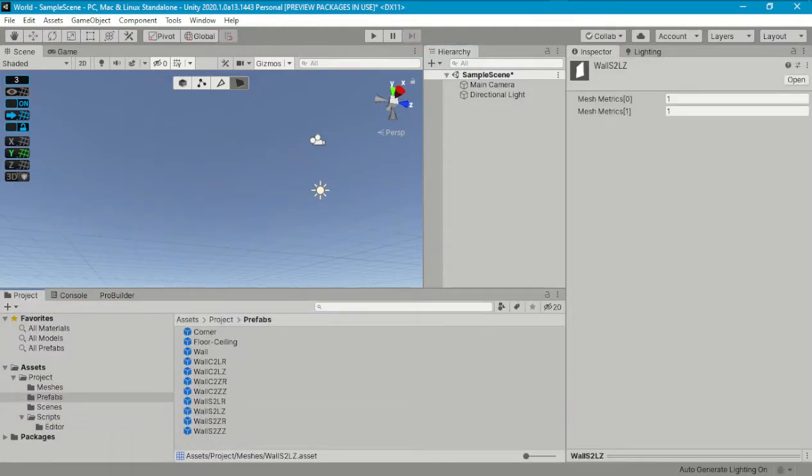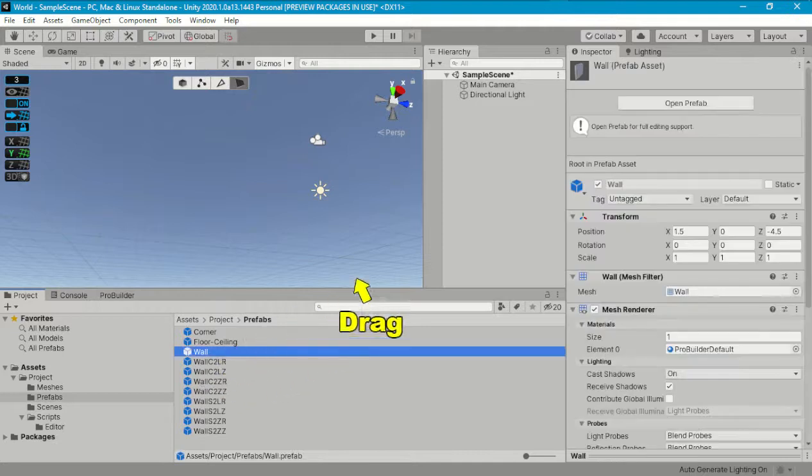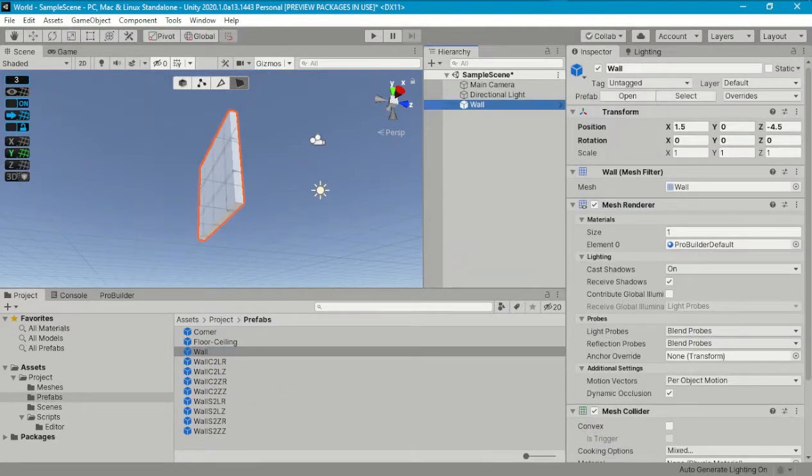We could say our wall tile set is complete at this point. However, most buildings have windows and doors, and none of our current tiles have any. So, we need to add more tiles to our set. Please bring the original wall tile onto the scene. We'll need to do some math on this one. Nothing complicated. Yet, it is best if we reset the transform to simplify the calculations.